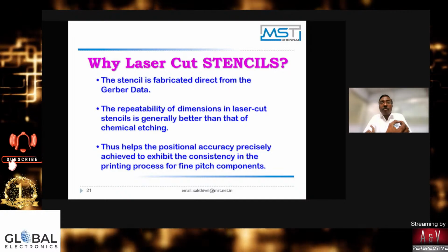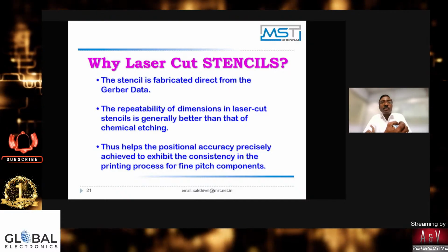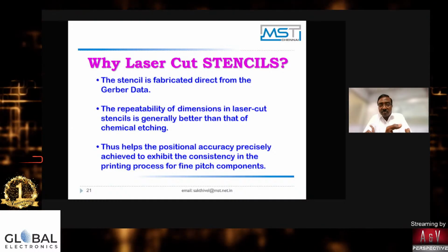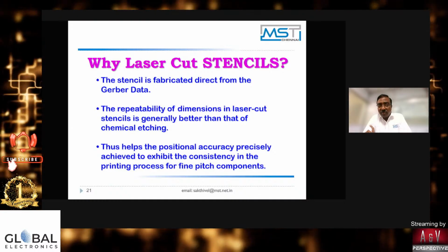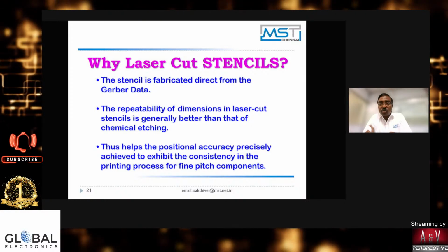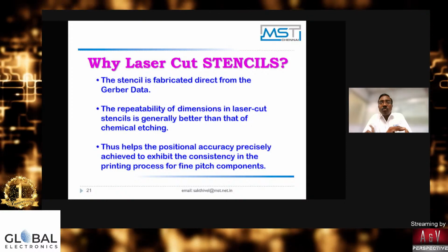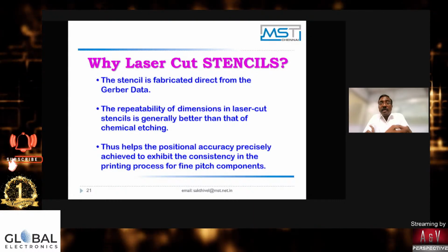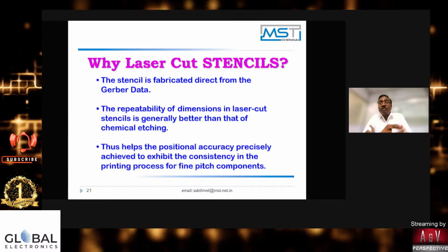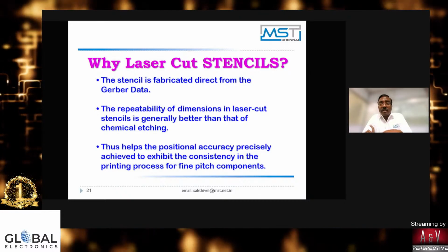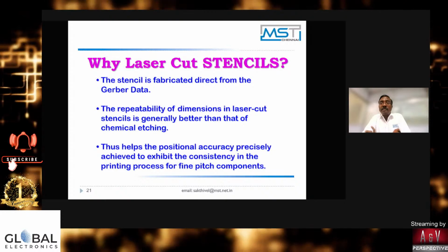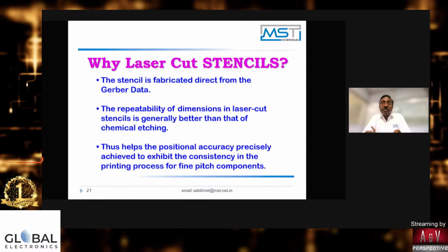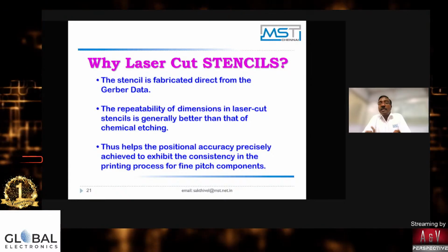Each component, the connector openings. Nowadays, the openings we have been finding are almost 0.12 or 0.15 in size, which is a BGA, where 0.3 or 0.25 is the pitch, and I could get 0.15 or 0.12 as an opening. So that way, you definitely cannot cut